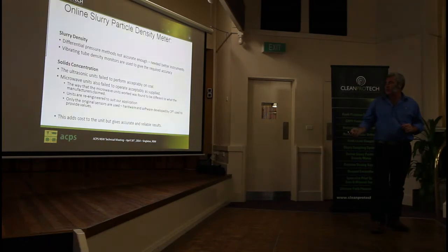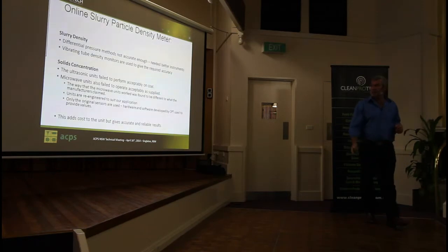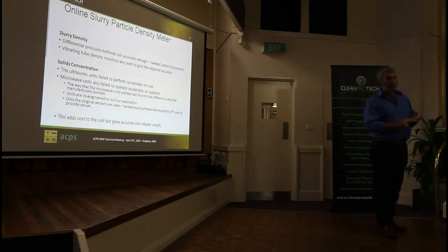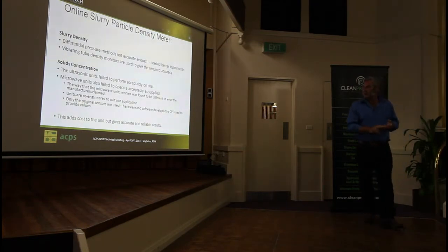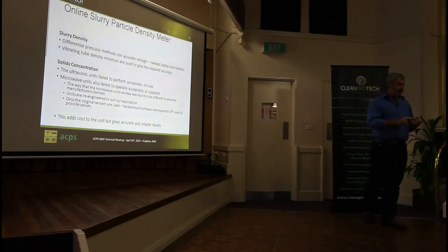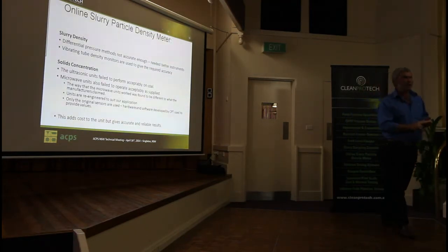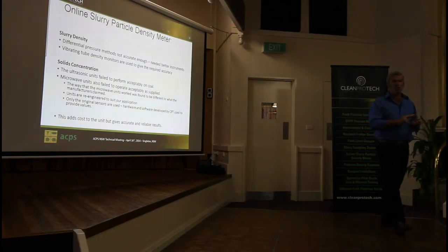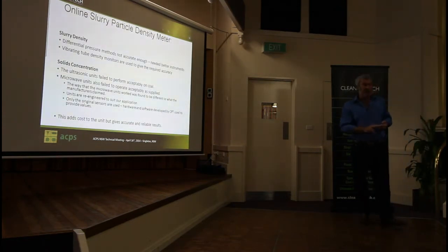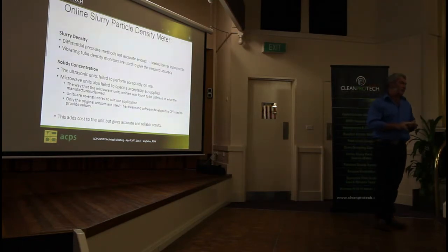Solids concentration proved more problematic, and we always knew it would be. The slurry density, yeah, that we can handle very, very well. Ultrasonic units we tried, they really didn't perform, for a whole stack of reasons. We then went to microwave units, a couple of different types, and these were something that we really had to do a lot of work on. We found that the accuracy from them was not good enough for what we needed for our device. We pulled those devices apart. We found that whilst they may work very, very well on solutions, on slurries it was a different matter.